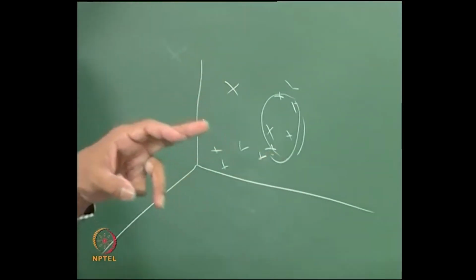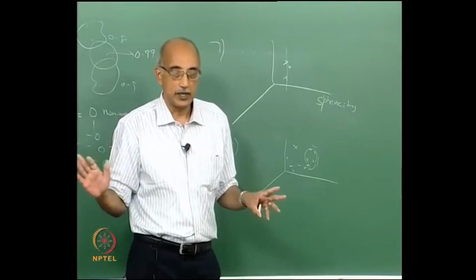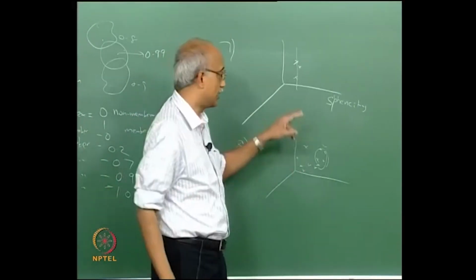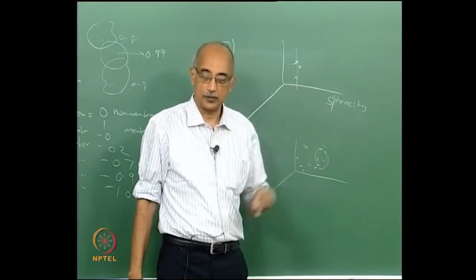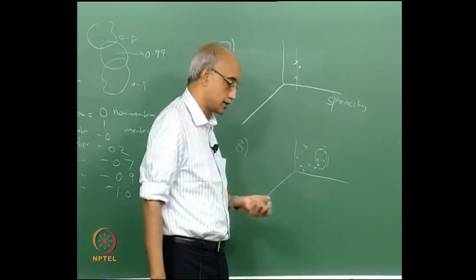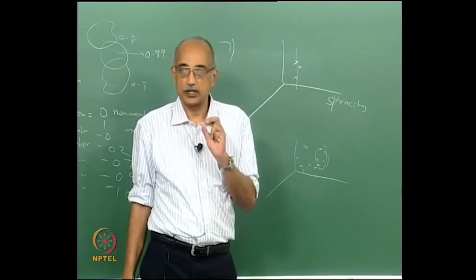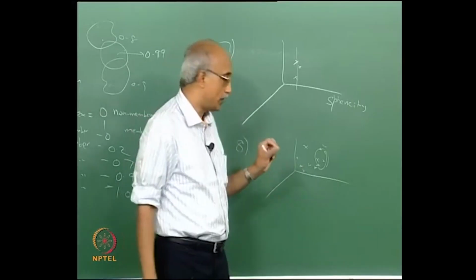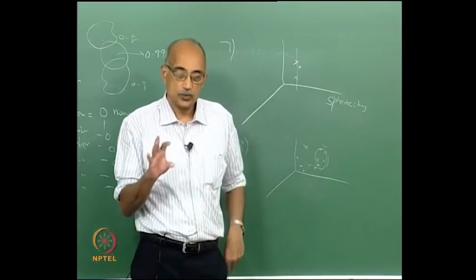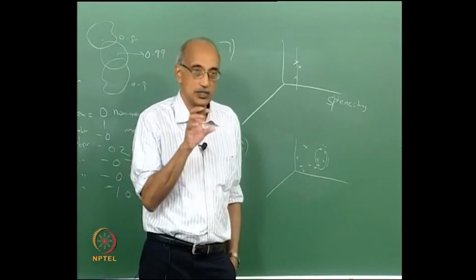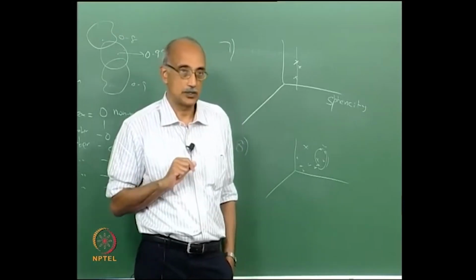The clustering approach works when you have more than one property that is relevant, but at the same time you do not want to do this in a purely empirical mathematical manner. You still want to carry over certain aspects of the common property approach, but in this case you identify the minimum number of relevant shape characteristics, and find out of all the shapes that you are considering which ones have the closest clustering of these properties to the particle that you are trying to analyze.